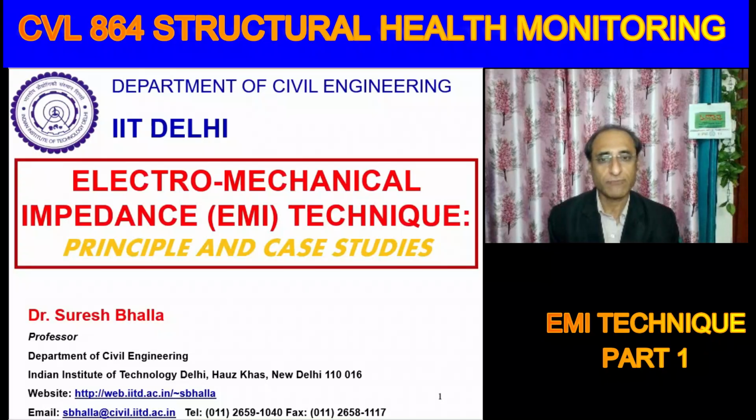So what we have recognized, and is also recognized by different researchers, we had covered a case study involving a real bridge which was being decommissioned. What they found was that for a small level of damage, there is hardly any change in the natural frequencies and the mode shapes, and there could be errors in our interpretation. Many of the techniques require human judgment to pinpoint the correct damage location, because the global vibration techniques rely on the global vibration modes. Global vibration modes are global in nature, so they are very less sensitive to incipient damage.